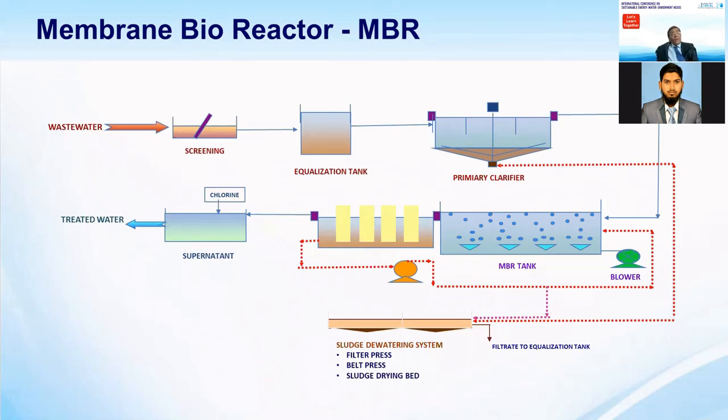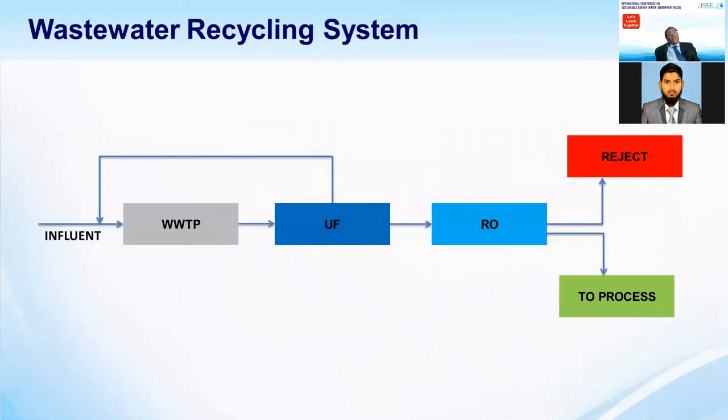I have two options. Let me see. Yes, this is the first. We should emphasize this slide. If we already have a wastewater treatment plant installed at any premises, then we have to install ultrafiltration membranes or a system to remove the suspended load of contaminants, and its objective is almost 80 to 95% recovery from the ultrafiltration membranes.